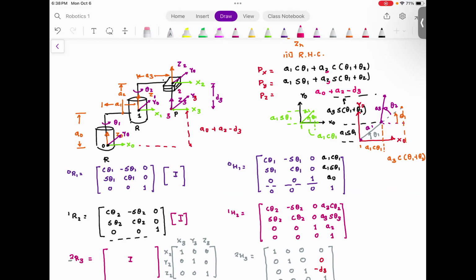So when we look at the forward kinematics equations, before you implement your inverse kinematics, look at the equations and see what coupling exists between them before you blindly use any Python solver or a MATLAB solver. Everyone understood this? So what is exactly D3?